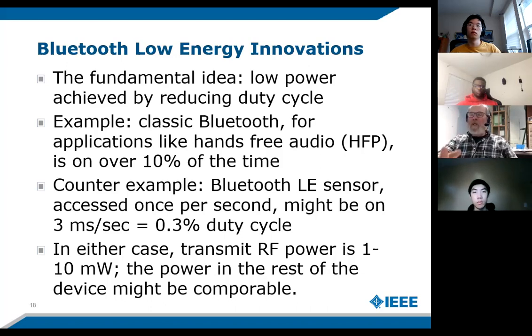So that's 128 kilobits. You'd think that's only 1/8 of the 1 megabit bandwidth, but there's overhead involved too. So its duty cycle for 1 megabit might actually be more like 30%. So it's burning power maybe 1/3 of the time.